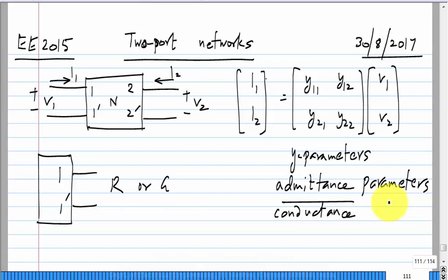So, this admittance is the same thing. It's analogous to conductance. It's the ratio of current to voltage, but not only for a resistance, but for storage elements like capacitors and inductances. Okay. So, clearly this Y is the ratio of current to voltage, right. So, if I had to write this, the current vector equals the Y parameter matrix times the voltage vector.